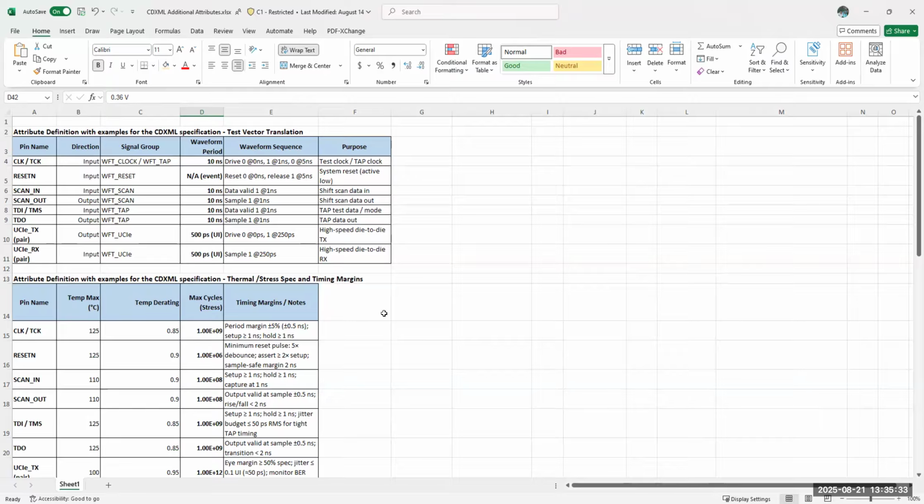Traditionally, we have used pattern retargeting in complex SOCs where the core-level patterns do not need to be regenerated at the top. They reuse all the core patterns like USB core and HDMI core, and when they go into the big SOC, the entire pattern retargeting works fine because finally you have only one netlist at SOC level. But at system in package level, has this tool been extended by anyone?